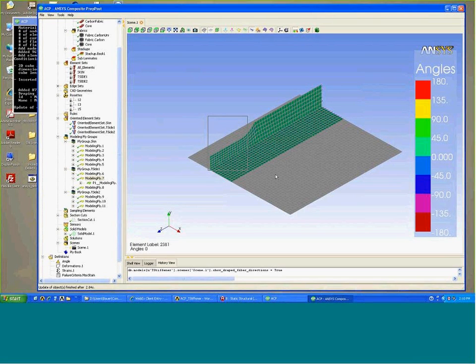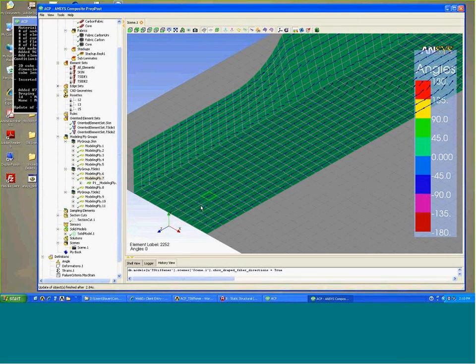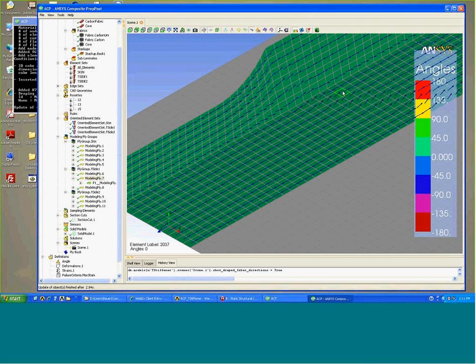If we zoom in here, we can look at how the angle direction starts from our corner based on our definition, and then the draping simulation shows some scissoring where the contour of this upright angle is kind of contoured up. So there is some change in ply angle based on our ply definition, our draping coefficients in this particular orientation.